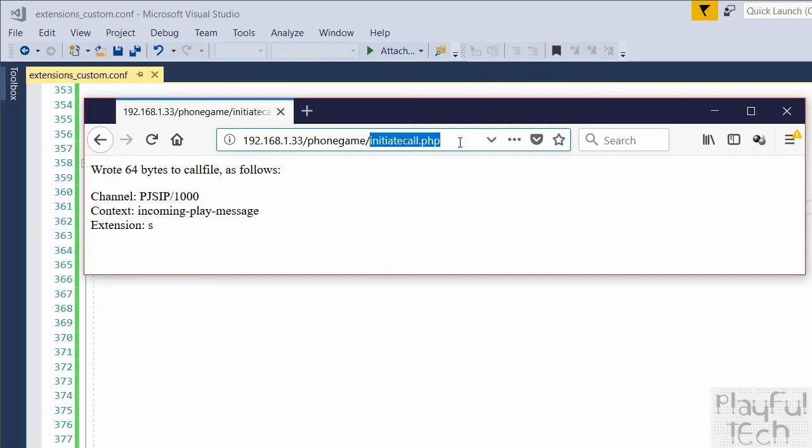Okay, and that was the script that gets called from the Arduino. Now obviously that message said this is your Arduino calling, which in this case it wasn't actually. This came from the web. So now let's have a look at how you would make an Arduino place this call instead. And to do that, what we need to do is to write some Arduino code that's going to make an HTTP request to this address here.